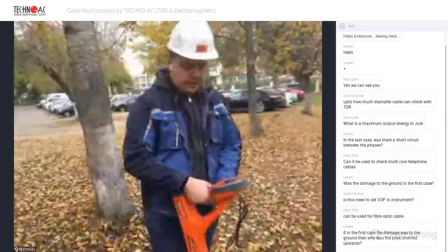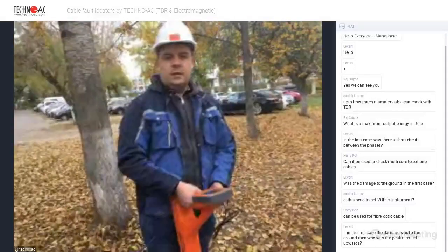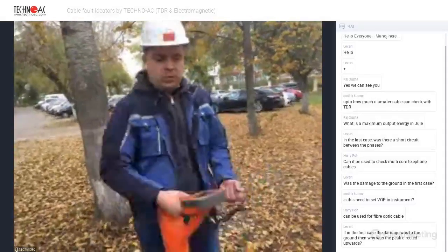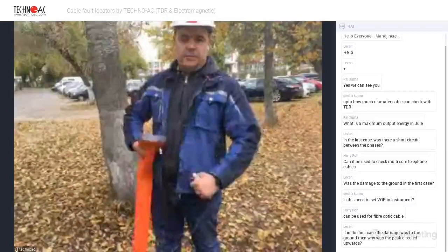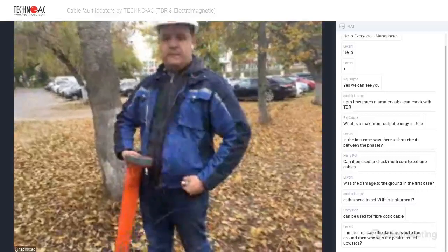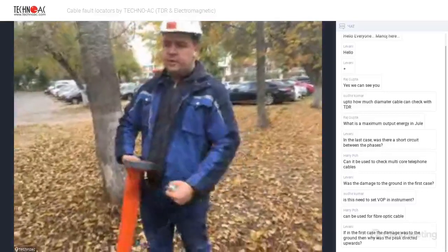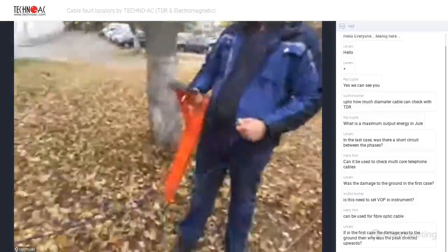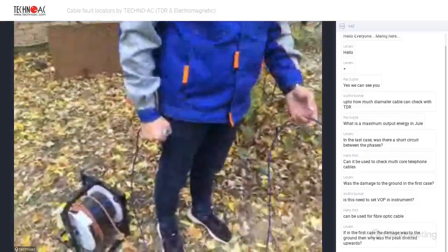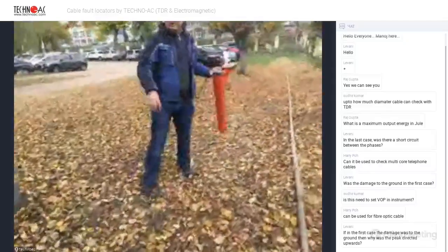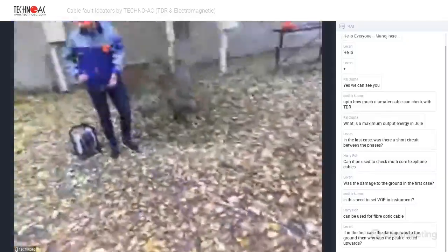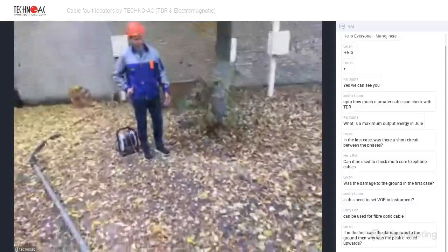And we're going alongside the cable. We have to be sure that we're holding our sensors on the same level. I advise to use it on the waist level so you can be sure that your colleague is doing the same. And what you have to do, you have to move with the receiver and sensor and make sure that the wire of the sensor is not touching ground.